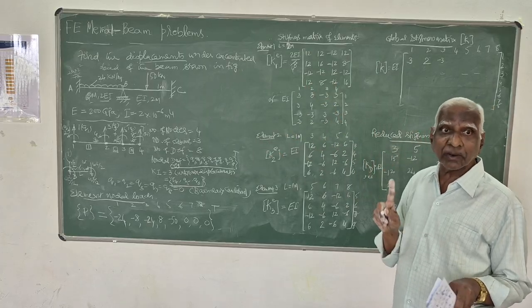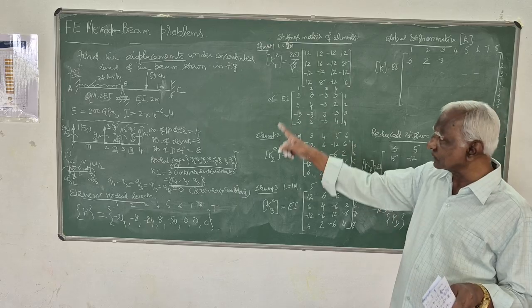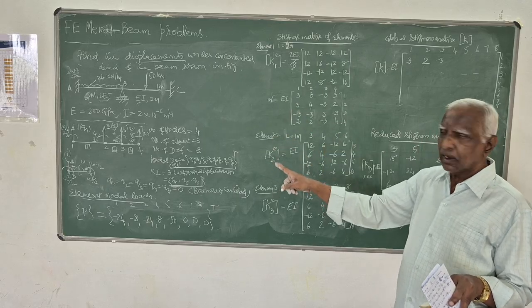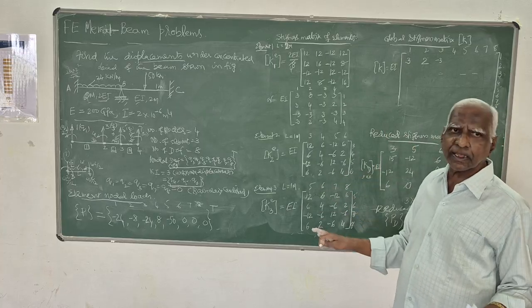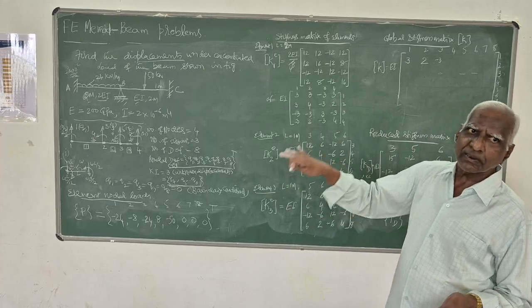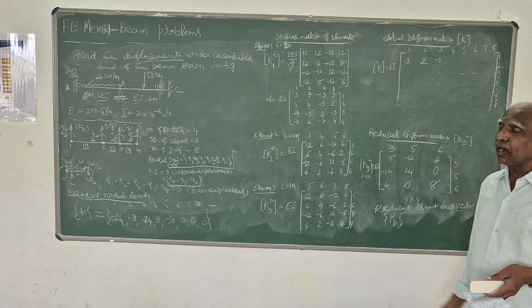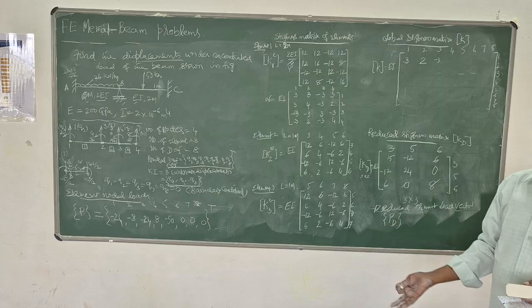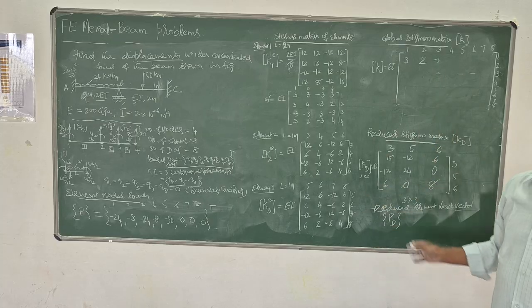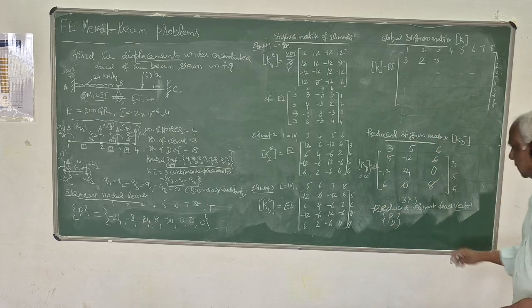That is very, very, very important. Whenever a concentrated load or moment is given on a member, you select a node there. If there is already a node, forget it. Otherwise, you have to impose a node, and it improves the element order, whether it is superparametric or subparametric.